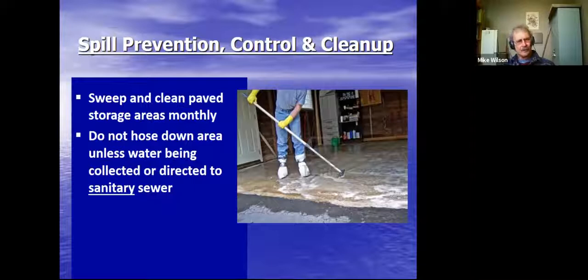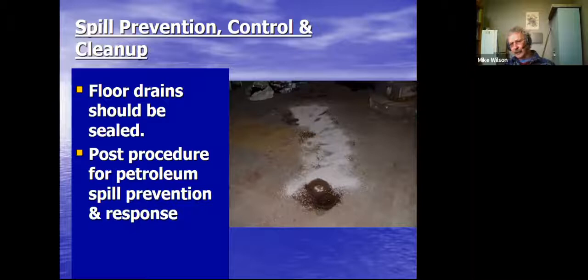You do not want to hose down areas unless water is being collected or directed to a sanitary sewer. You do not want to go down a catch basin, that's for sure. All your floor drains actually should be sealed unless they're going to a proper cleaning facility, oil water separator or sanitary storage system. And there is a post procedure for petroleum spills in terms of prevention and response.